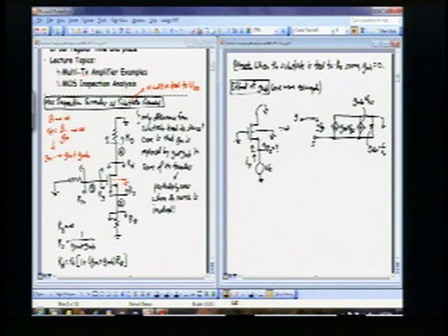In addition, I'm driving this bottom terminal with this Vx test source. So there's my Vx test voltage, and I want to measure this current going into that. So Vx is plus and minus around that. And then finally, where's my bulk terminal? I'll draw it out here. We've grounded that bulk terminal, so that's B. This is D up here, the drain terminal. But the bulk terminal has a voltage across it of plus to minus here, and that's my VBS voltage.